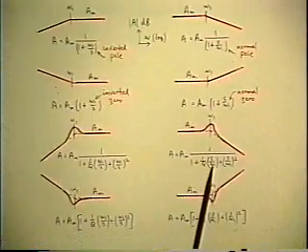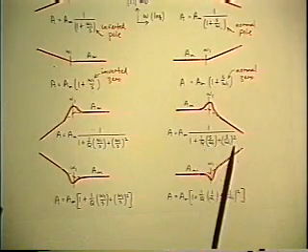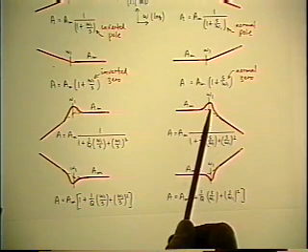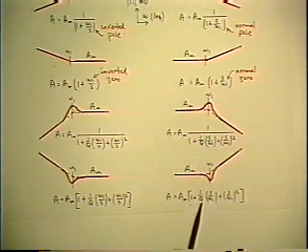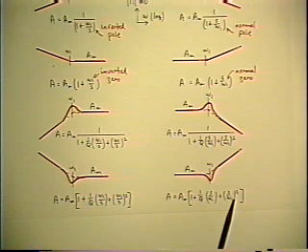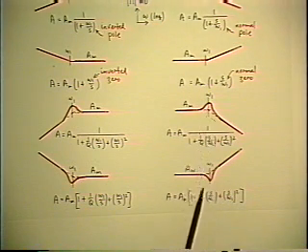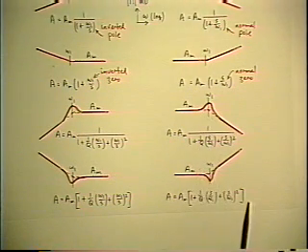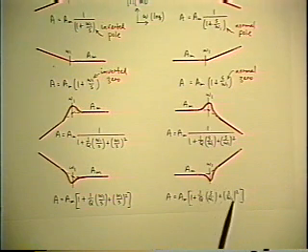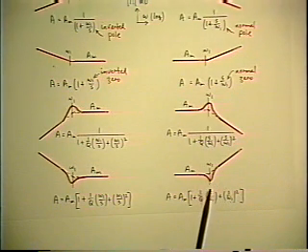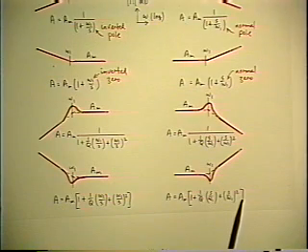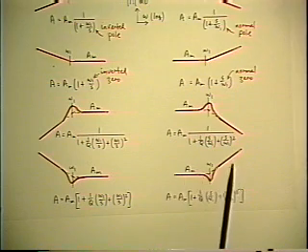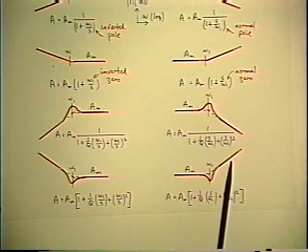This is the quadratic we've discussed, namely the denominator quadratic that results from the RLC filter. It's a low-pass filter. Of course, the quadratic could very well show up in the numerator. And making use of the vertical inversion properties, we'd now have a pair of zeros. But the geometry remains the same. You can either have a complex pair of zeros if Q is bigger than 0.5, or you could have two real zeros. And the geometry separates them the same. The zeros would be Q omega 1 and omega 1 over Q.